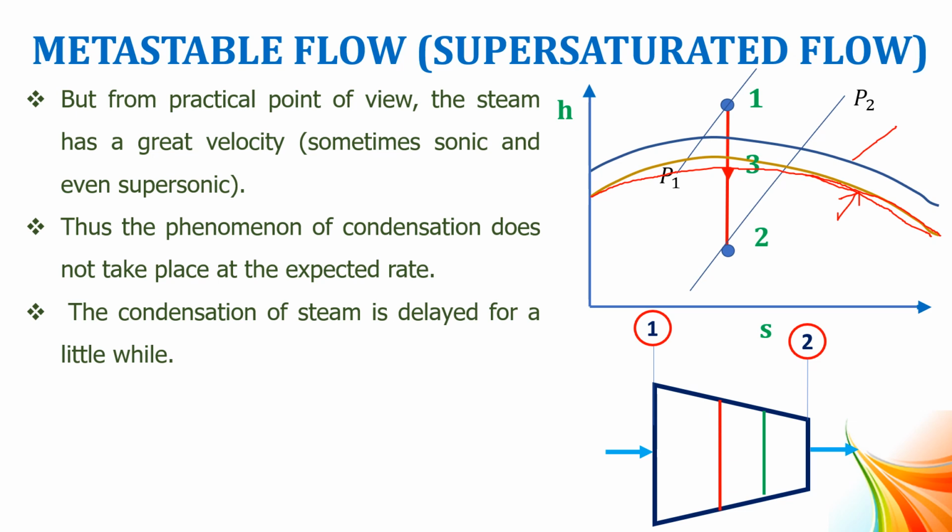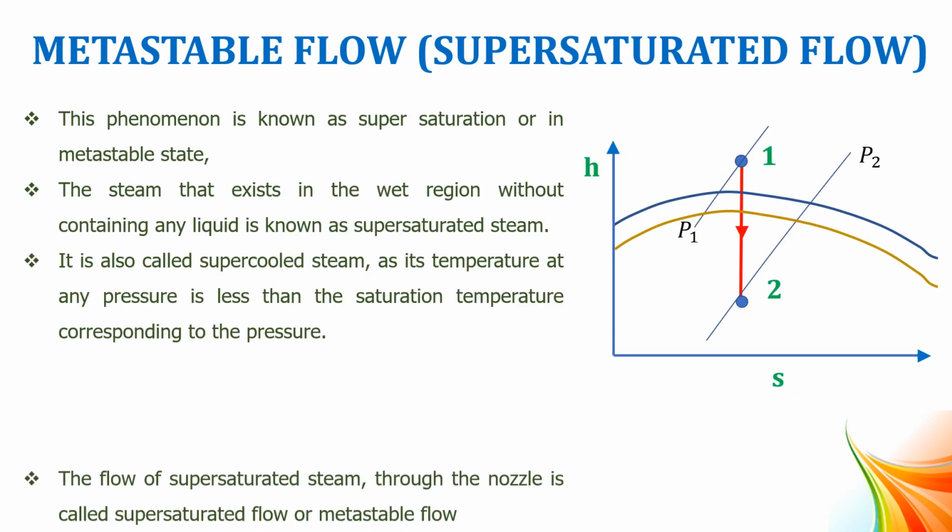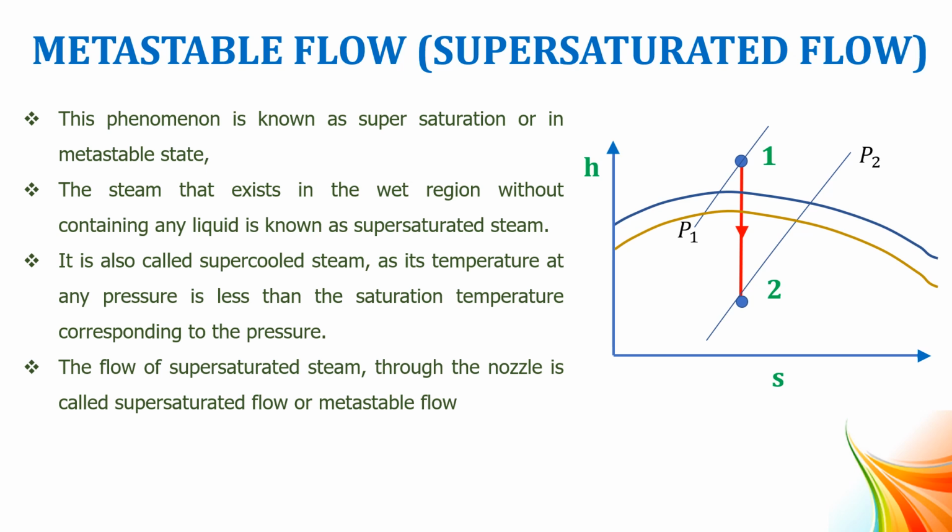The condensation is delayed for a while. As a result of this delay in the condensation, equilibrium between the liquid and vapor phase is delayed and the steam continues to expand as dry steam. That is called supersaturation or metastable state.